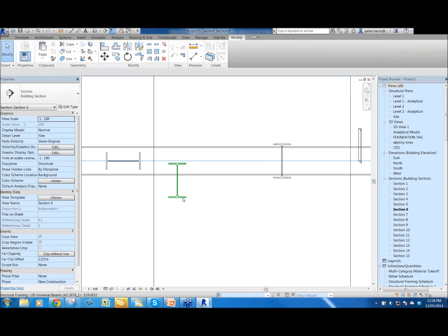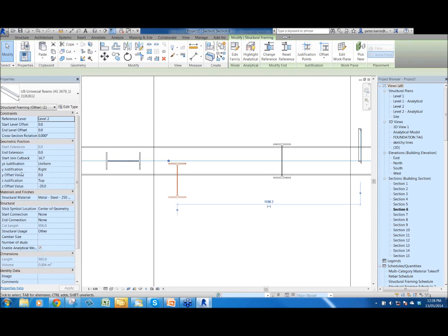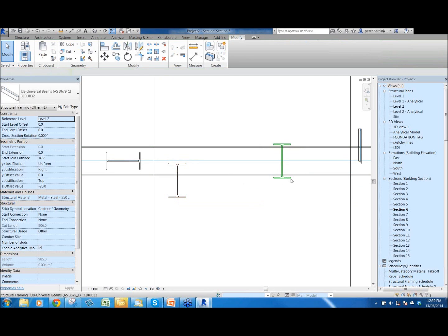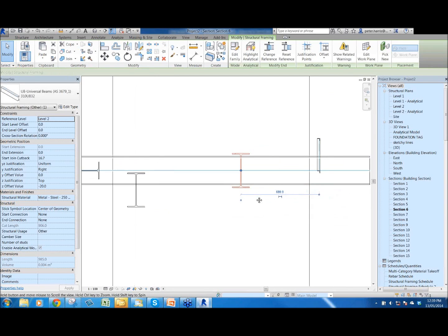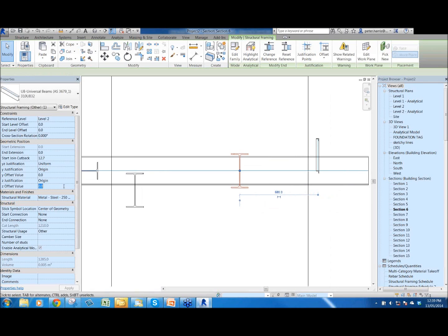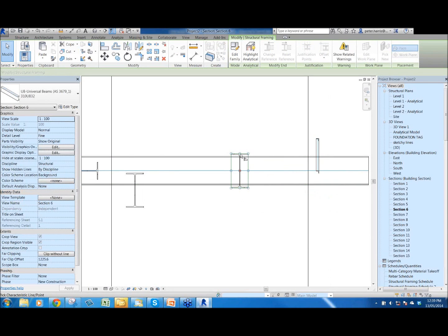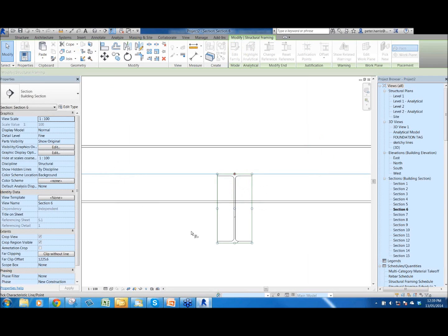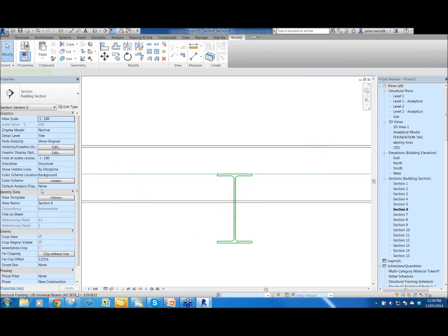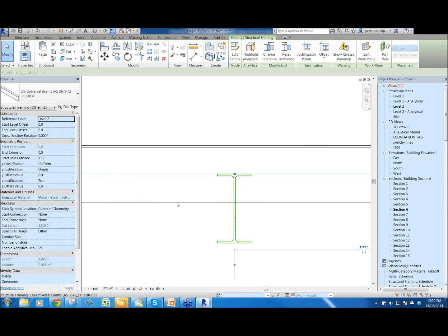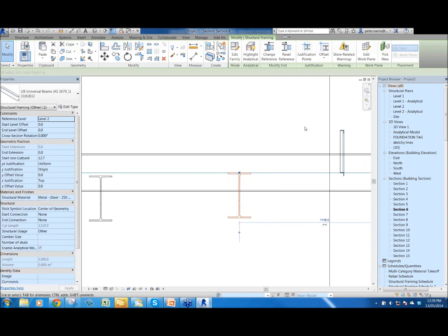We always could at any stage select a member, and at the moment you can see in this case it was Z was right, Y was right, and top. So according to what it is, I might come over here, see if I've got a center one. Yep. So if I change, there it is. Everything's origin, origin. If I now go justification, I can change to be the top. And what that's doing is essentially changing this over here. So just a lot easier graphically.